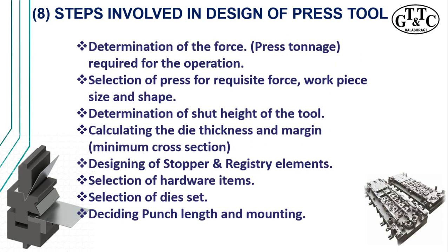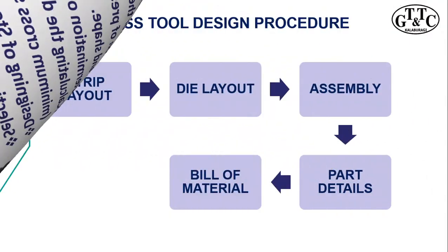And then if the accuracy is very high, it is always advisable to go with a ball cage rather than a plain pillar and bush as a guide post. And then deciding the punch length and the mounting, so how you are going to mount the punches. All these things have to be taken into consideration before you start with the actual designing.